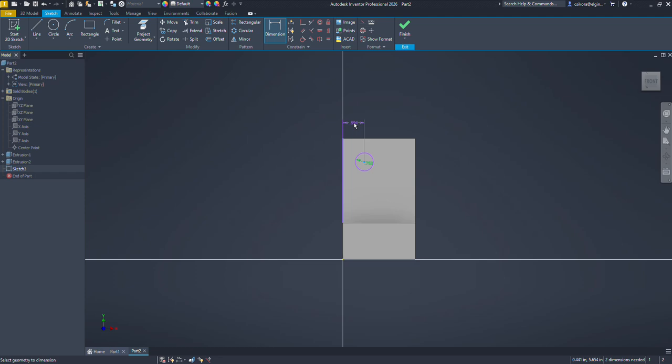Some of you might not have any experience dimensioning, but typically when you make a drawing or dimension, even for the future, someone else might want to edit this. And so you need to make sure it's laid out in a way that's legible, just like if you were to write out a paper about something. It's a language in and of itself. So go ahead and click first, sorry, and type 1. You don't have to type 0.000 in this case because it's just 1 inch straight. Hit enter or the green check mark, and now it's positioned 1 inch off of the edge.